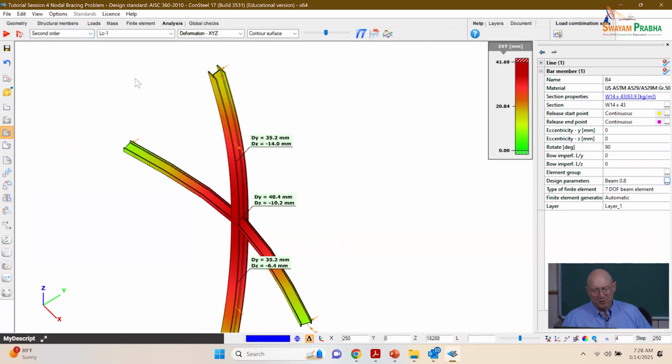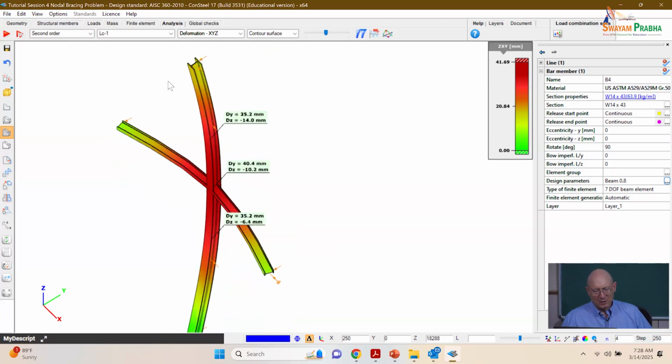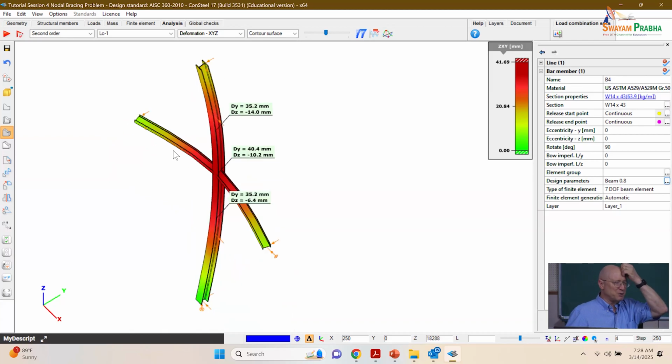Now, if we look at just a couple of other things here in Consteel, one thing that we would still need to do, but in the interest of time we won't work through that, in general we would need to check that the W14 by 145 column, if it's bent into a mode that is an S shape, if it has an imperfection that's an S shape with an inflection point at the brace, that's the way that would be most damning in terms of imperfections on the column.